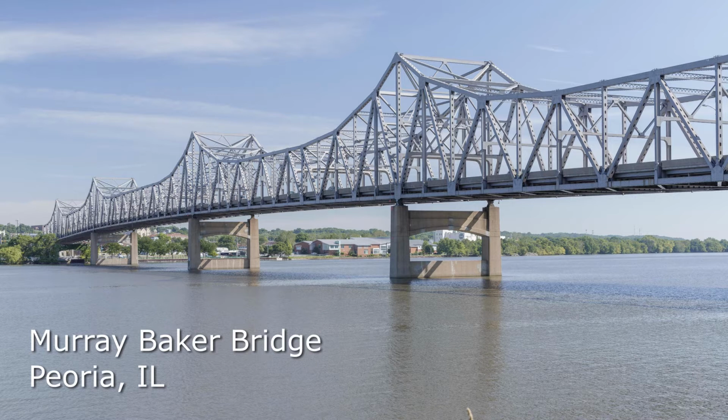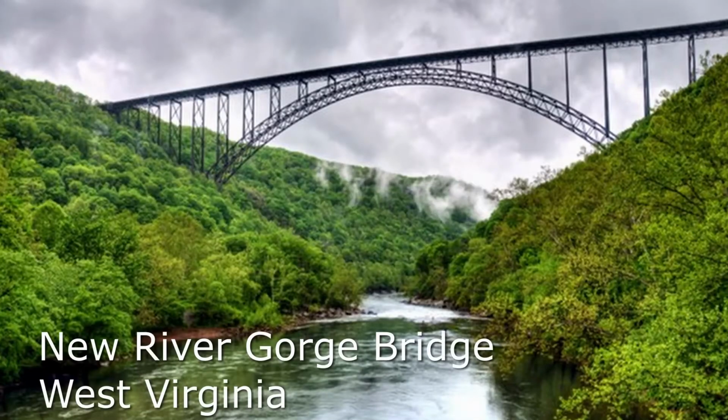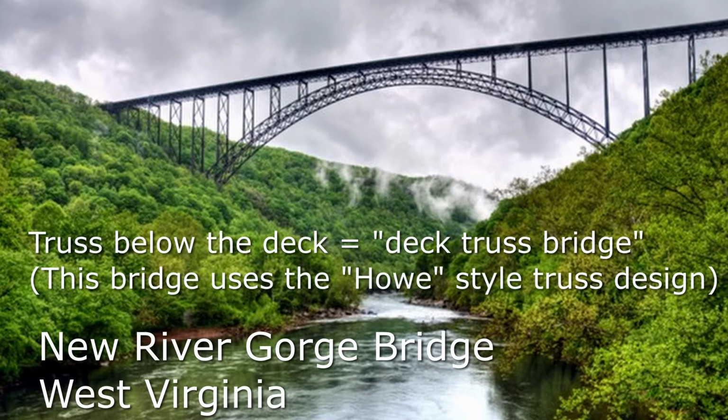So some truss bridges have the truss over the top of the bridge, like the Murray-Baker Bridge, and some trusses actually have the truss placed beneath the bridge. But no matter where your truss is placed, it helps support the beam along the bridge deck and uses the tension and compression distributed throughout the various beams of the truss to spread the forces along the beam so no one area bears too much of the load.